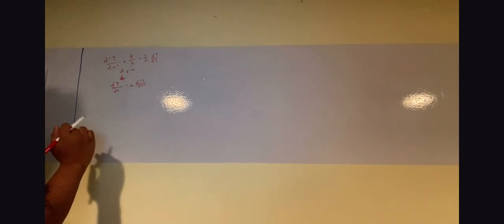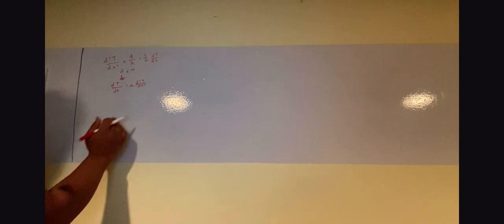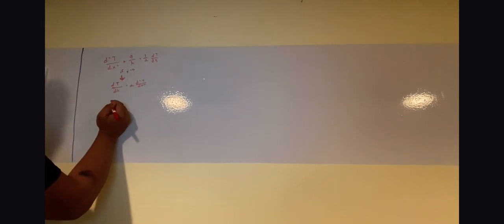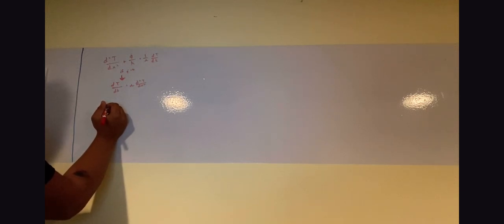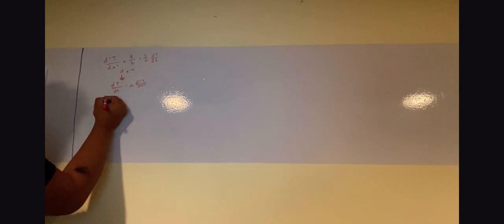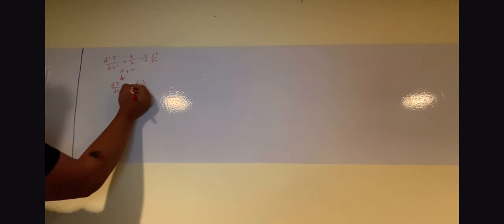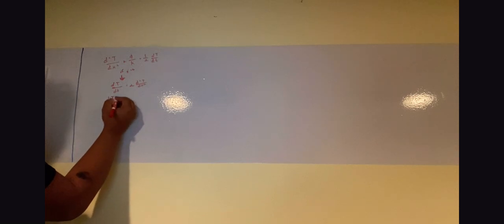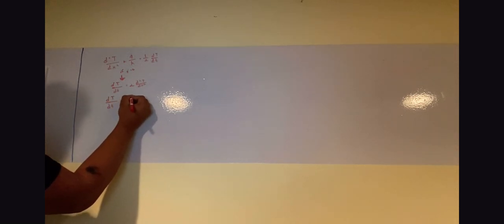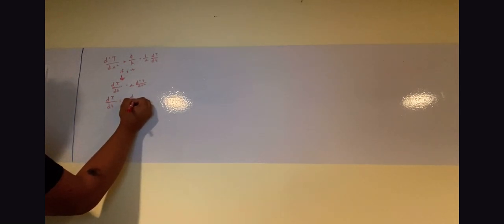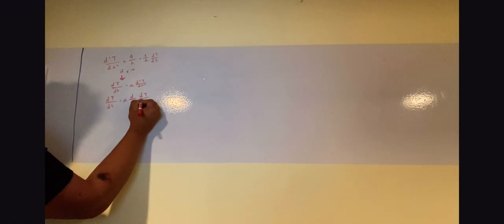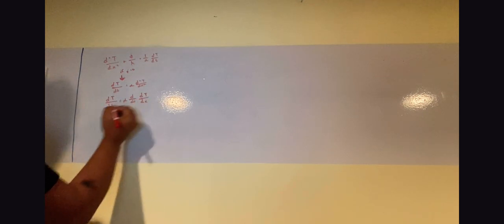So now we're going to use finite difference, and the first thing that we're going to do is break this into two derivatives. When we break this into two derivatives, we have dT over dt is equal to alpha d over dx times dT over dx.